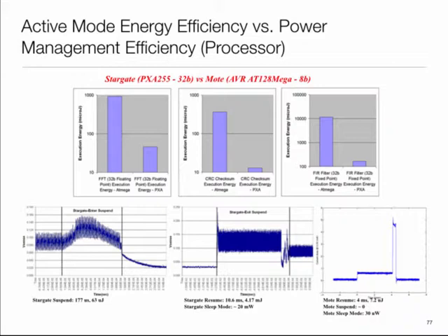So pretty good. But when you compare it against the low power device, this guy takes 4 milliseconds to boot up, consumes only 7 microjoule of energy while waking up, and during sleep mode it consumes microwatts. So clearly if I have tasks where I need to spend long periods of time in sleep and wake up frequently, it's a better strategy to let this guy do that kind of work and put this guy to total power shutdown.